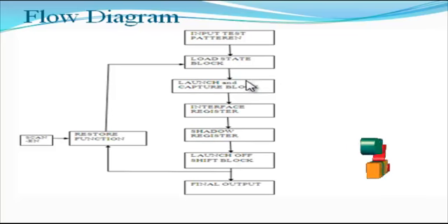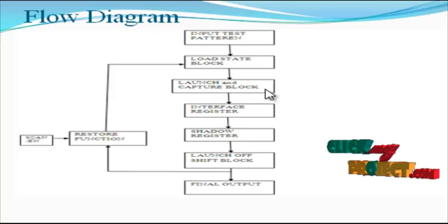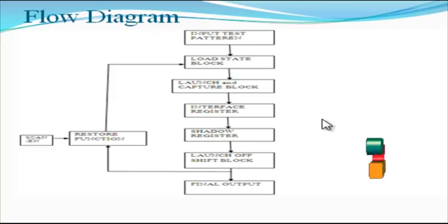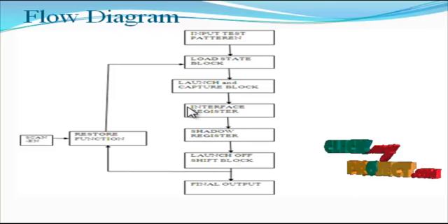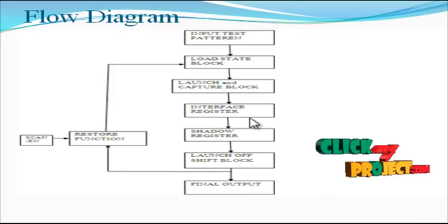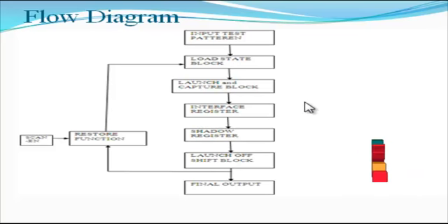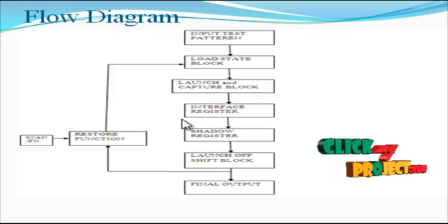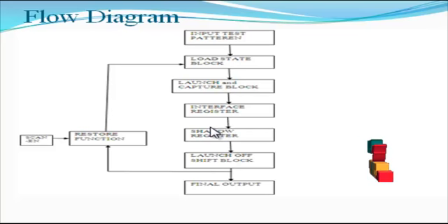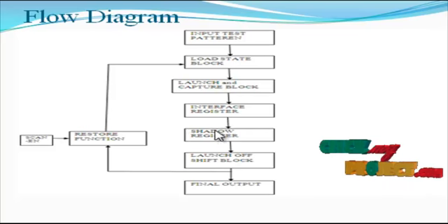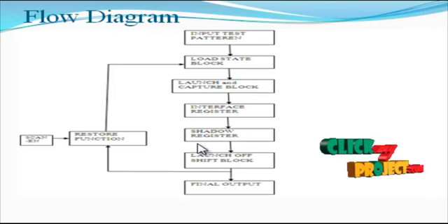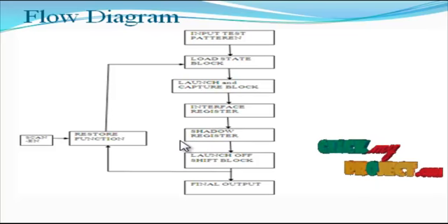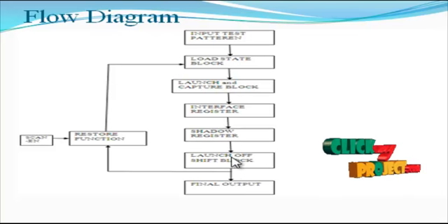The LOC block is processed by our testing architecture. Thus, the architecture passes to the interface register. The interface register is a clockless register element, and a latching process is applied. Thus, the input is just stored in the interface register and passed to the shadow register. The shadow register finally holds the final test pattern results. The final test pattern results are stored in the shadow register and used to apply the launch and shift operation.